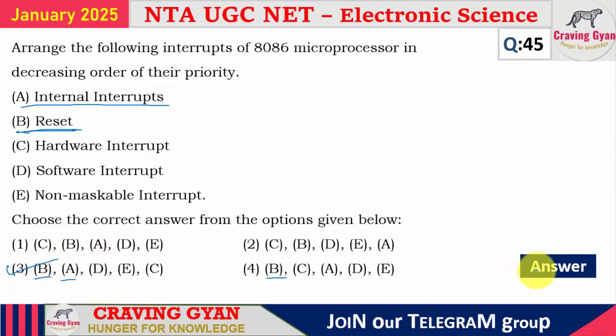So the corresponding option that's going to follow is option 3 is correct, right? Now it should be followed by software interrupt, then it should be followed by hardware interrupt, then it should be followed by non-maskable interrupt. In the case of a decreasing order, if I am arranging, look at the things carefully. Hardware interrupts will be having the lowest priority, right? Hardware interrupts will be having the least priority. But you please consider non-maskable interrupt also they have given at large. Whether this question is valid or not, you ask yourself.